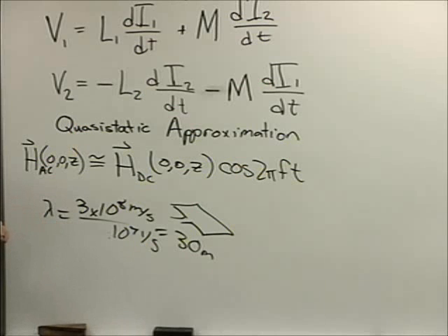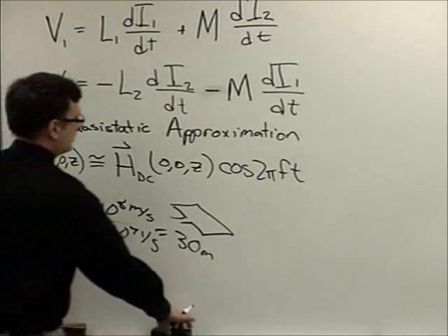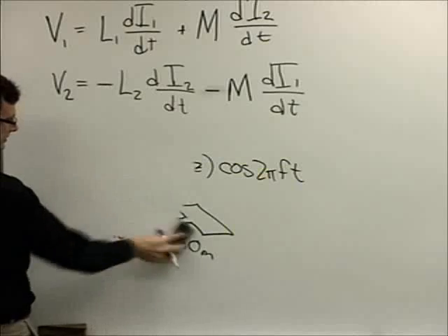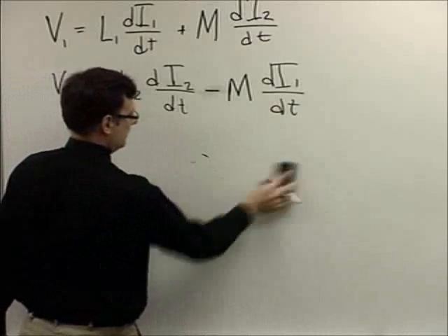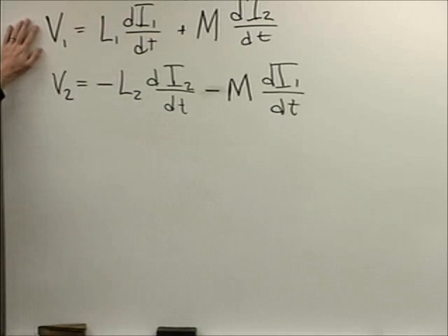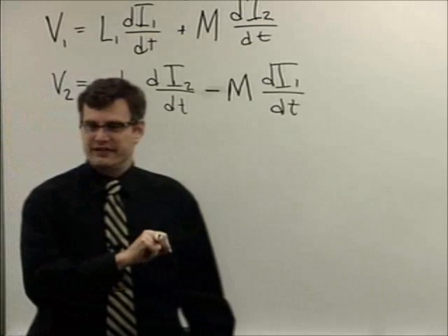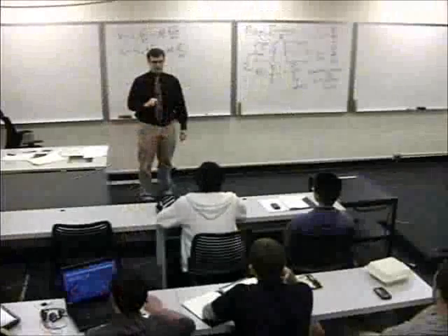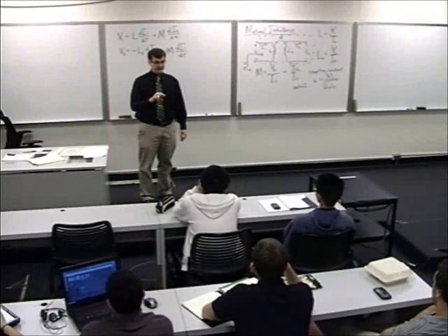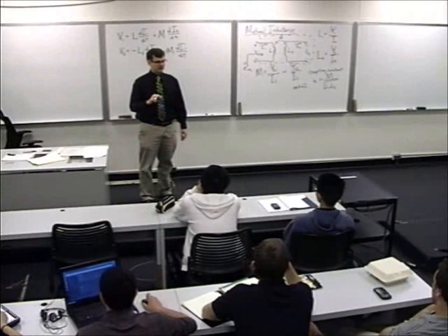Okay. So let's convert these equations that I put up here into the phasor domain, because ultimately that's what I want to do. We want a sinusoidal system. How do you convert a derivative into the phasor domain? What do you got to do? It's kind of like a Laplace transformation, yeah.